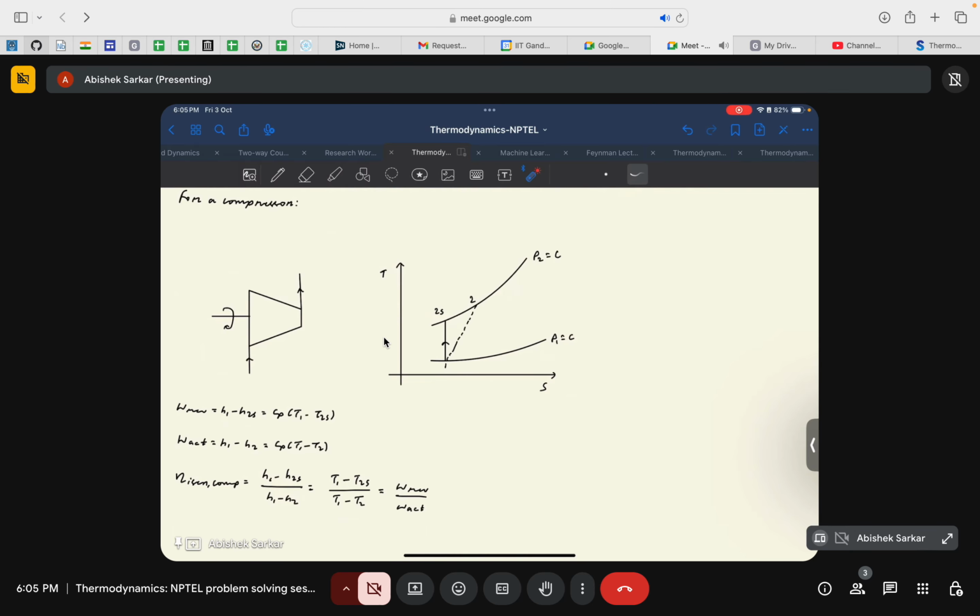We could see that there was a discernible change in the enthalpy because of the pumping of the fluid from lower pressure to a higher pressure. If you consider the working fluid to be, say, an ideal gas, I'm just giving an example, it does not have to be an ideal gas, but the change in enthalpy becomes solely a function of temperature. So let us look into it.